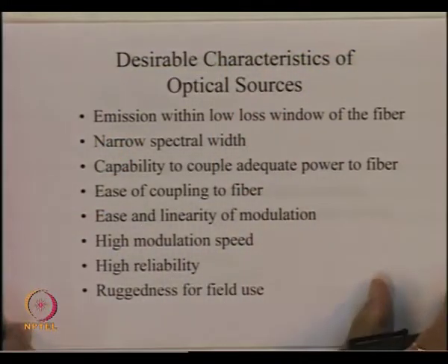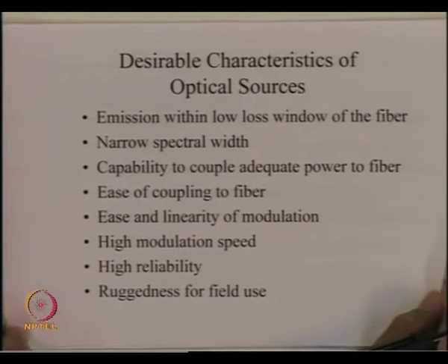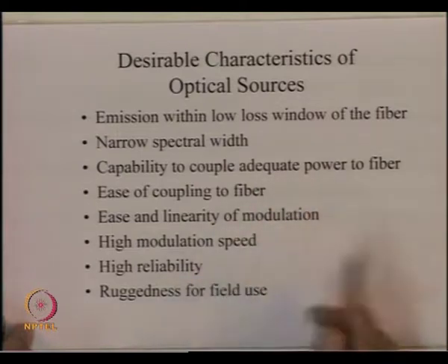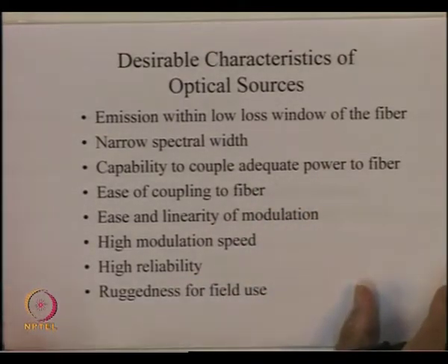inside the optical fiber. So, if I consider only the first two aspects of the optical sources, then the gas sources may be quite appropriate because they satisfy these two criteria very satisfactorily. But if I look at the other feature which I am looking for in optical sources, that it should be compatible with the optical fiber, it should also be integrable with the electronic circuit which we are going to use, then gas sources are not very appropriate sources for optical communication.